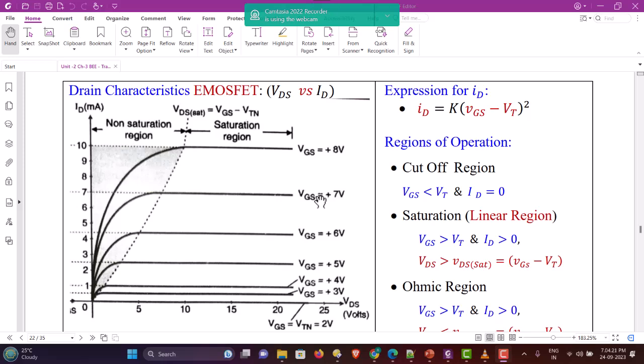The reason being, the electric field of VDS is such that the channel width is sufficiently high, and decreasing VDS further towards zero reduces the draining electric field on the channel carriers. Therefore, if the draining electric field is less, the number of charge carriers removed from the drain are less, and therefore at lower values of VDS, the current is decreasing.